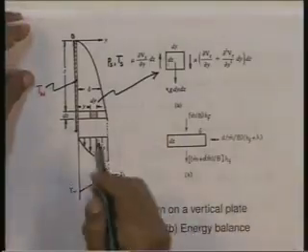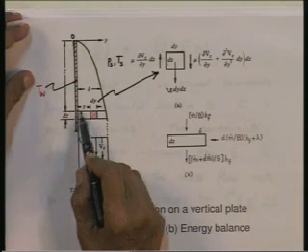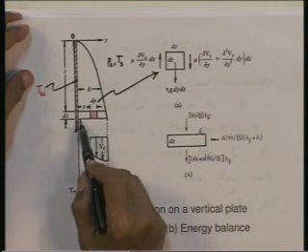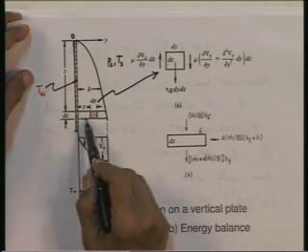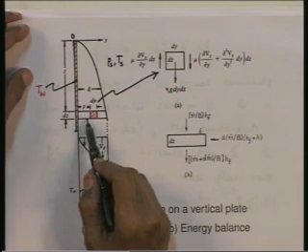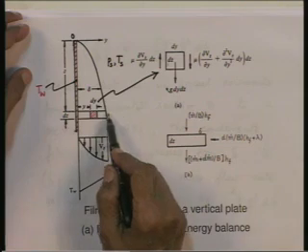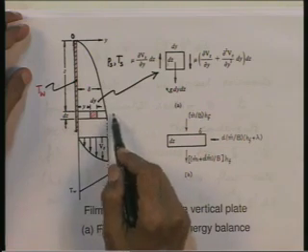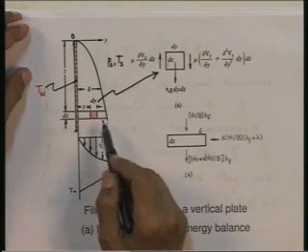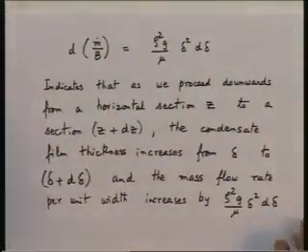Or in other words, let me again go back to the sketch I showed you. If I go across a cross section Z here, I know m dot by b. If I go down a distance here, the m dot by b increases by a certain amount, and why is that increase occurring? Because condensation is taking place. So, in other words, the condensation rate per unit width from Z to Z plus dz is rho squared g delta squared d delta upon mu.